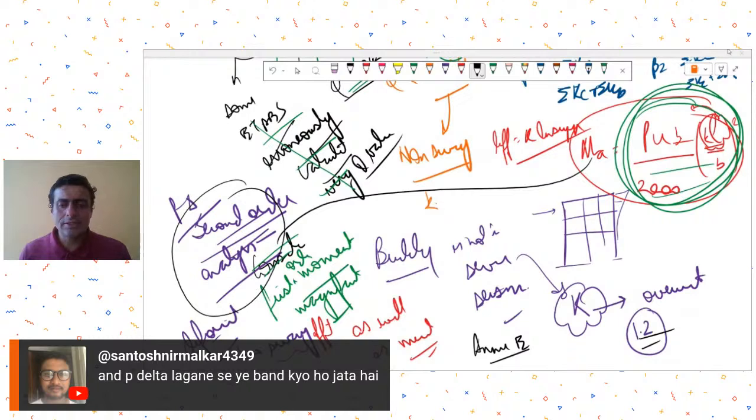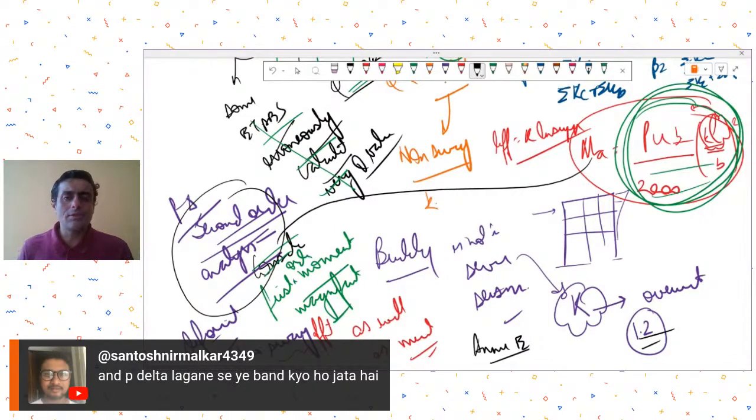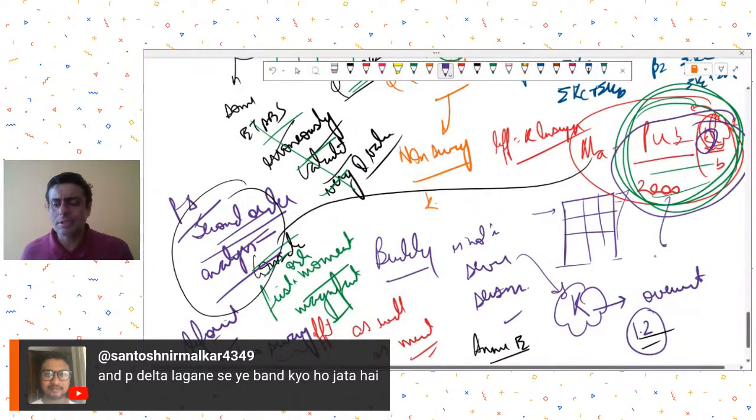So that is the reason why when you include P delta analysis, the software will not consider the K value calculations. Do you understand? I will just slightly correct myself. It will not do the K value calculations, but it will still do this additional moment because this is what is called the P small delta effect.